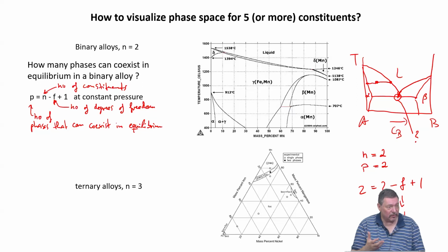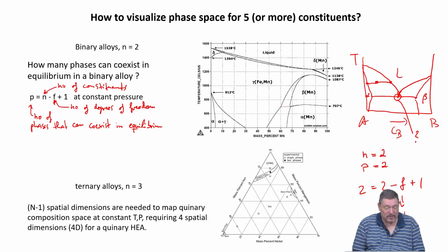Especially when we are talking about high entropy systems, we talk about multi-principal alloys, right? So it's not that you have a dilute solution of 10 elements in one major element like in steel. No, you have many, 5, 6 components which have almost equal concentration. And that means you are going to the center of this multidimensional phase space, phase diagram. And that means you should know and should worry about all possible phase equilibria present and about how to display them.